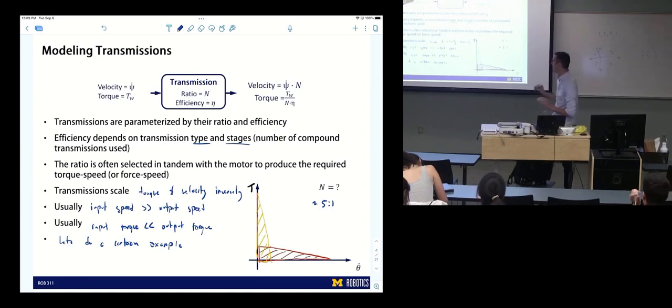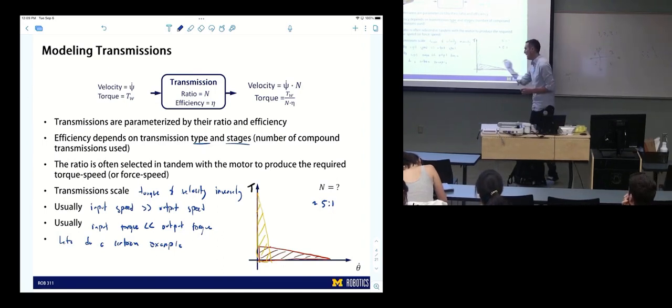I think you should be able to look at this and identify the transmission ratio broadly, with ease. That would show you that you have an accurate understanding, or the understanding we want in this class. So that's a little cartoon example. Any sort of region that existed in torque-speed would be scaled this way by any transmission ratio. This is how they work. Scaled torque and speed in this way. We're just looking at it in the torque-speed plane right now. Cool?